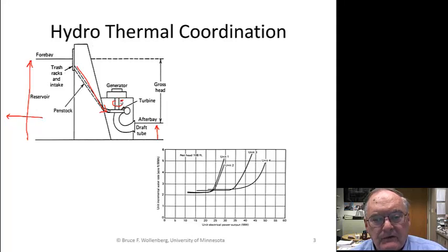Notice that this particular one that we've drawn, the water here is going in here and then down here out this so-called draft tube into the afterbay. It doesn't spin anywhere near as fast as you do for a steam electric unit or one that's like a combined cycle unit where it's gas turbines. It's spinning much slower, so they'll have many more poles, so that they can still deliver 60 hertz electric energy from these generators, but they are spinning much slower.